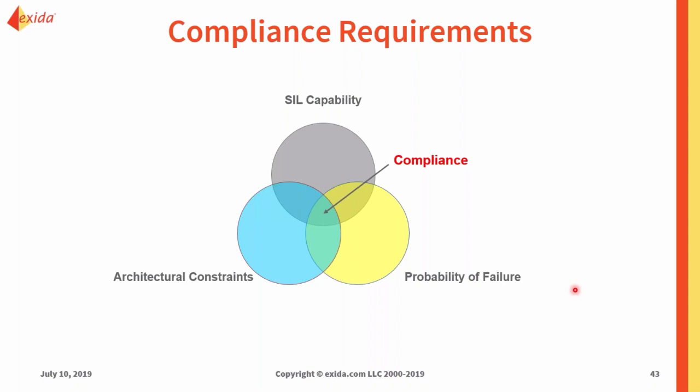Next, if you have a low or not good enough PFDavg, maybe that's your limiting factor. If that is, remember that huge equation that had so many variables in it for PFDavg. There are lots of different variables that you as an end user can control. Looking at proof testing, change your proof test interval, change how complete your proof testing is, maybe change your mission time. All of those can boost your PFDavg to possibly hit that next goal.